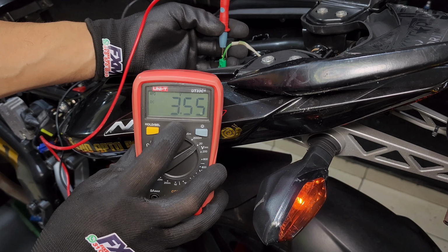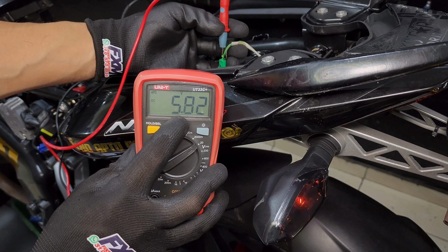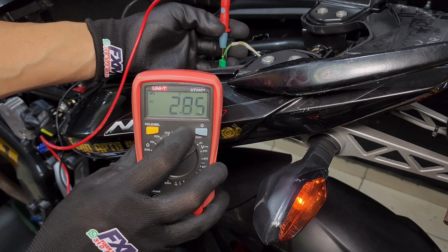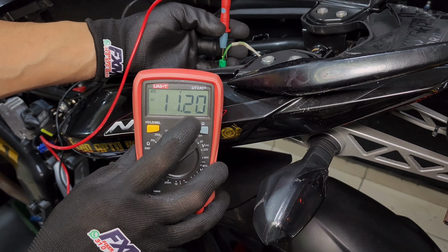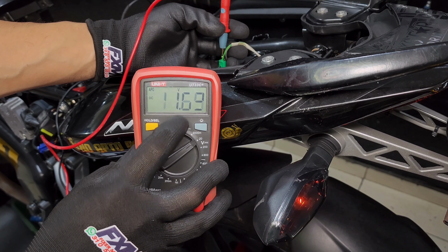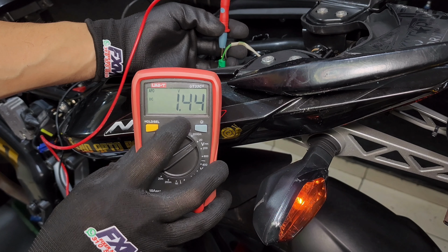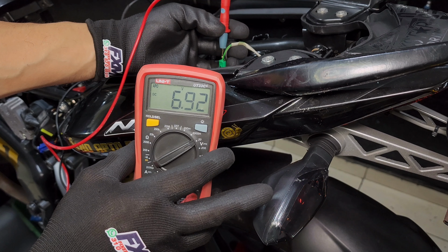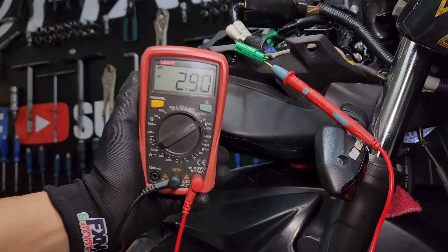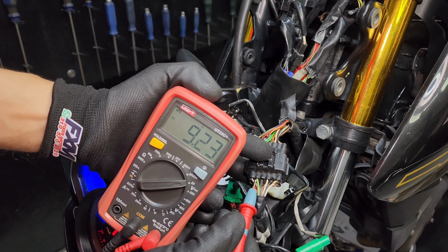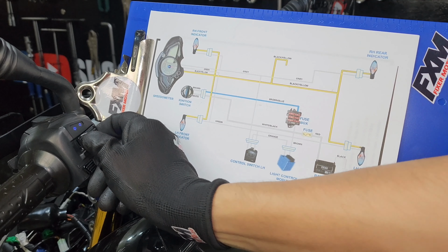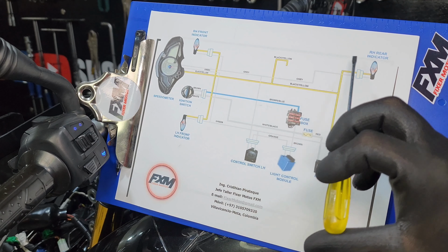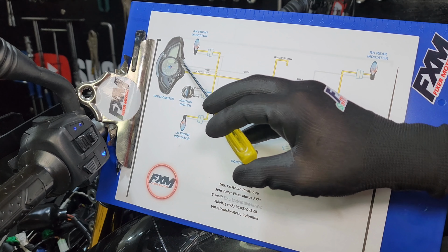Still, the voltage is not static because the light bulb is turning on and off. There, what the multimeter is doing is taking an average between the minimum voltage and the maximum voltage because it doesn't have the capacity to take the reading and update itself as quickly as the turn signal light bulb is on. Here it should give us the same voltage at the instrument panel indicator. And when you turn it to the right, it comes out through this gray cable, the same to the front, to the rear, and the instrument panel.